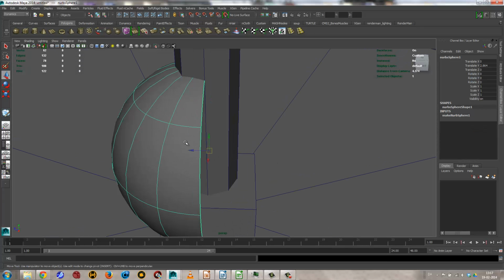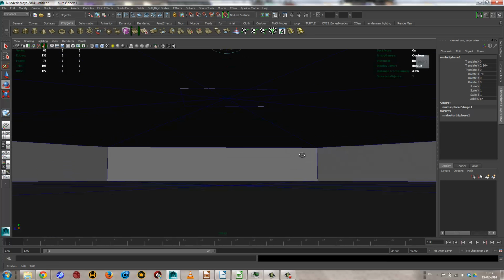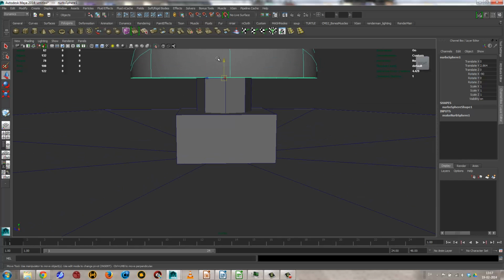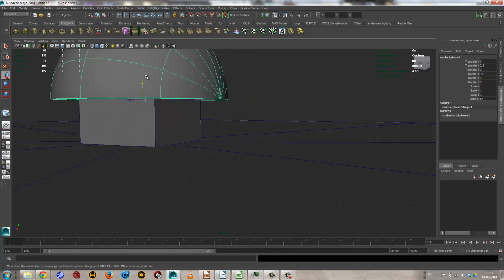And then I want to rotate this, so I'm going to select that, select my rotate tool. In this case I'll hold the J key. The J key will make discrete rotation work, so it'll snap in 15-degree steps, so something like that. There you go, and then I'll just move it down. And if I'm smart, I'll actually select this line here, so that the Y-axis is the one that is active. Then I'll hold the V key for snap to point, and then middle mouse button drag to this point over here, and you can see that it snaps to the vertical position, because that was the axis that was active, to that point.